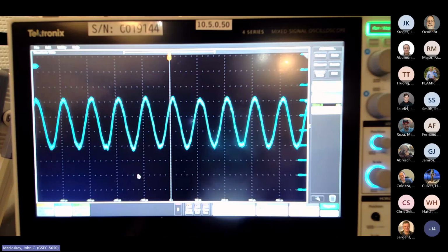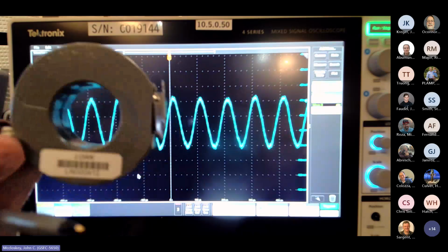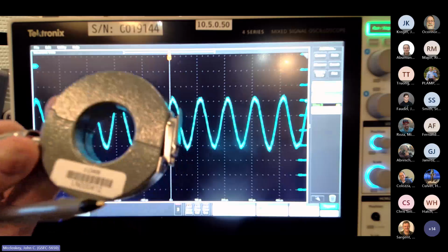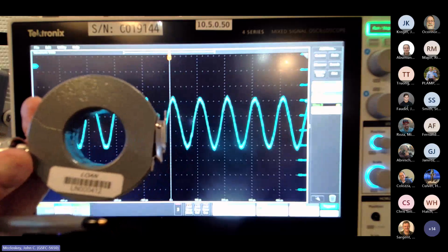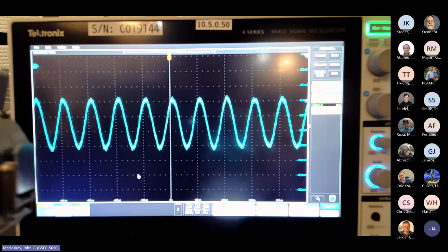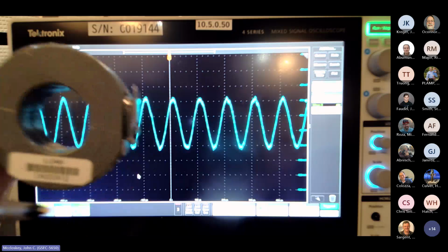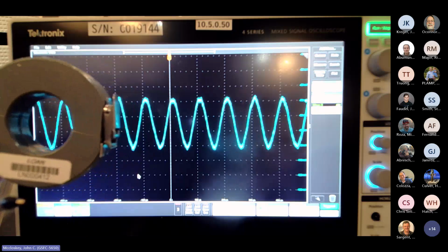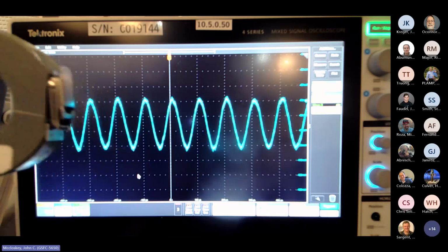That's an interesting point. I'll come back to it when we get through these measurements, because of the standard current probe that I would be inclined to use. This is the current probe I like to use for time domain measurements because it's got a flat response, but only above about 100 kilohertz. So down at this frequency range, it's still going to give you a compromised reading. When I looked at it with this probe the other day, the signal level was much cleaner.